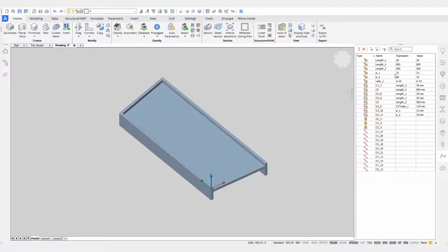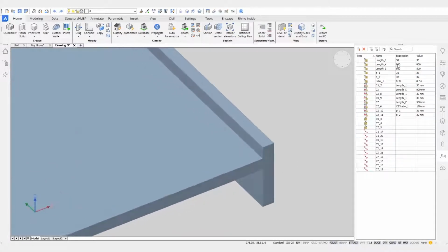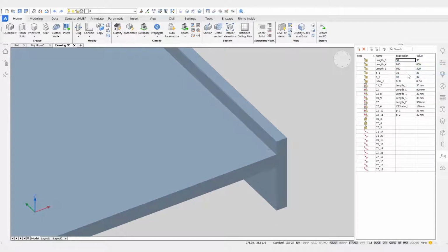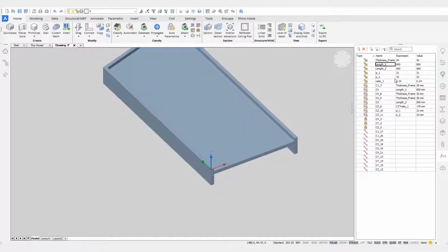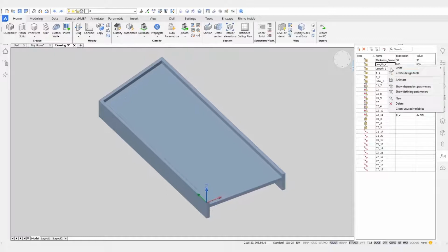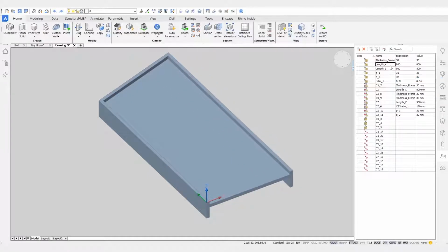And now I should be able to see what happens if I animate this parameter, for instance. See, this already looks better, because automatically it created the constraint between these two faces so they stay parallel, things like that. So I can start renaming my parameters. This one is angle top, for instance.